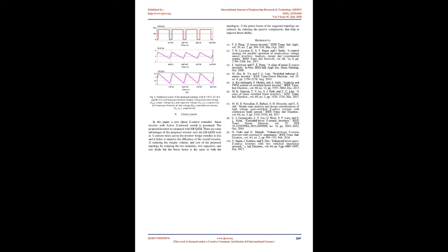The values of both the inductor currents 1 and 2 increase linearly in the shoot-through state, as shown in Figure 5b. In the non-shoot-through condition, the inductor current decreases linearly. Accordingly, the above operational criteria in the section are well confirmed by the analysis of the simulation.